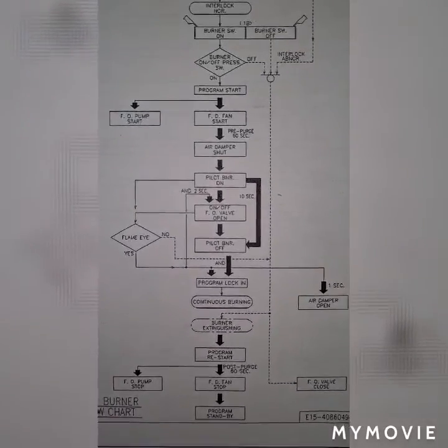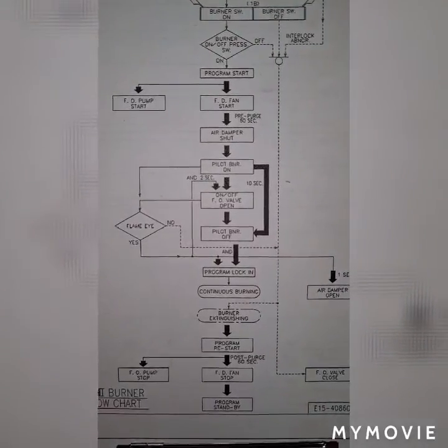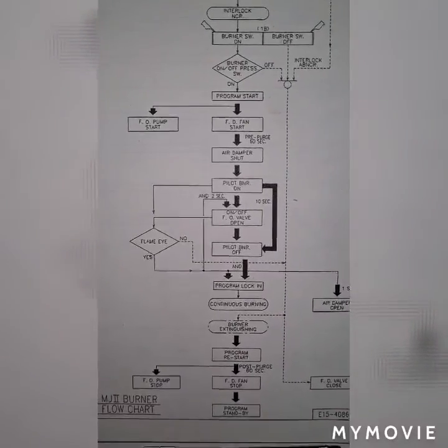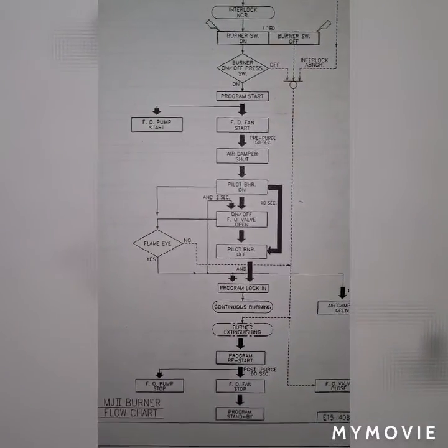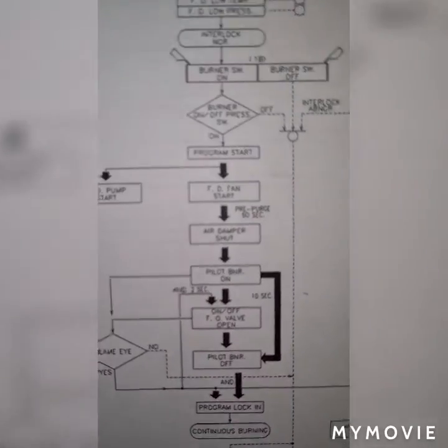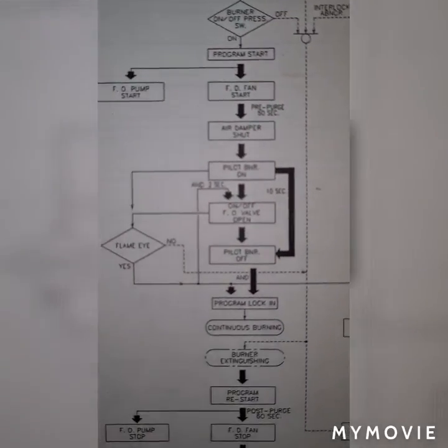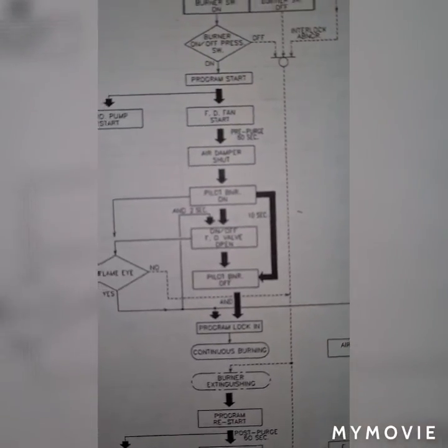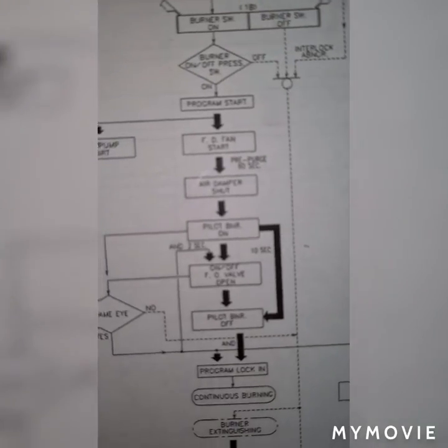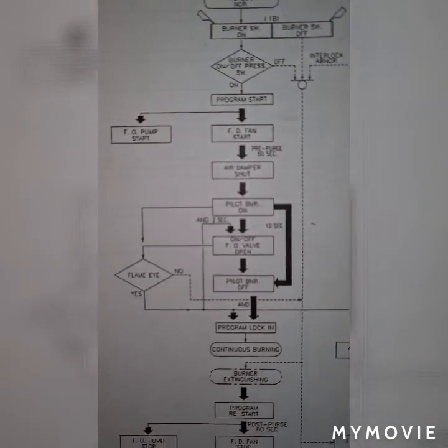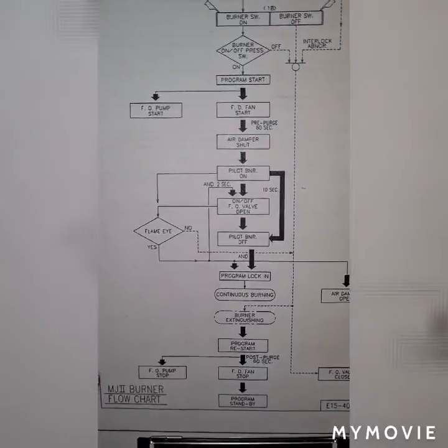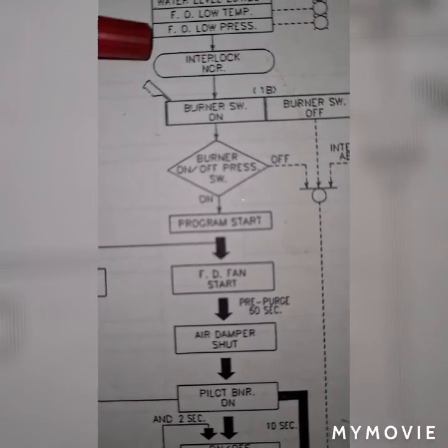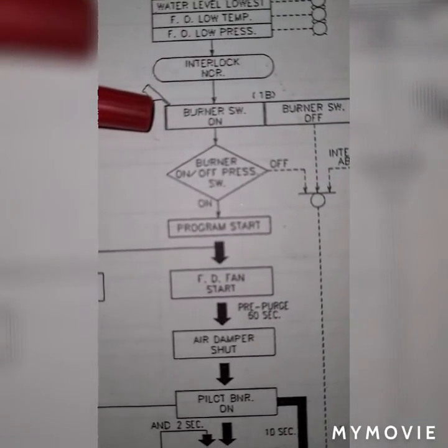Okay, this is the process flow chart of the boiler pre-PLC sequencer module. To start with, since my boiler is programmed with a maximum pressure of 0.59 megapascal, and this steam pressure drops to about 0.47 megapascal, the mode selector switch of my boiler is in automatic mode.